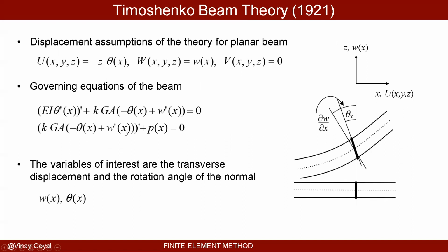In my book, I derive these equations using the total potential energy, and you can actually do that and get to the same results. The finite element formulation can be derived in that manner. So these are the governing equations. Let's look at that carefully. E is the modulus, I is the moment of inertia.